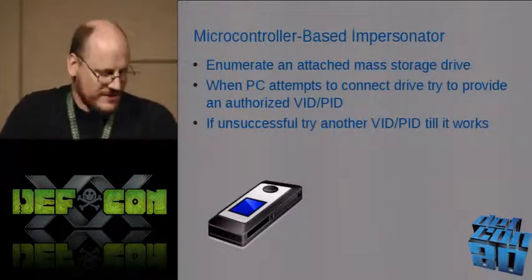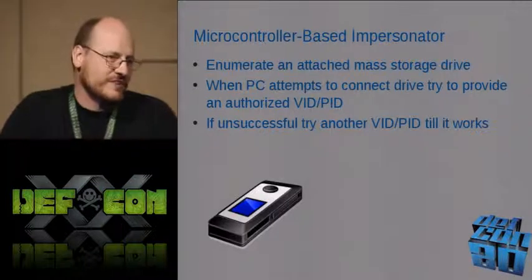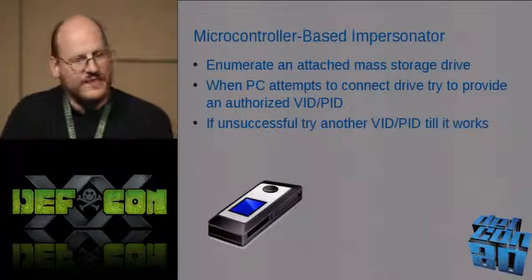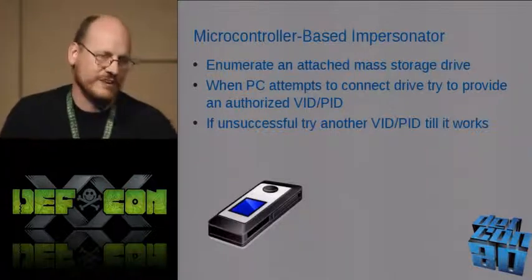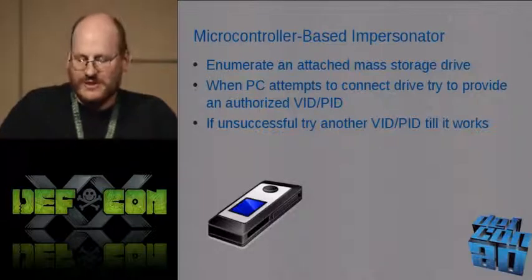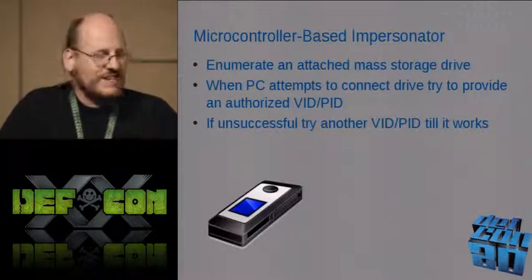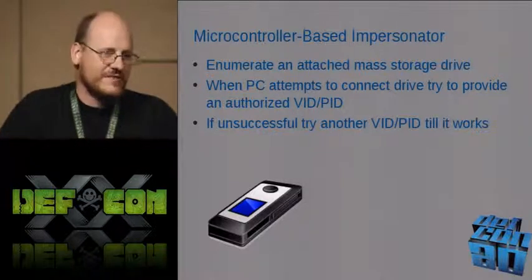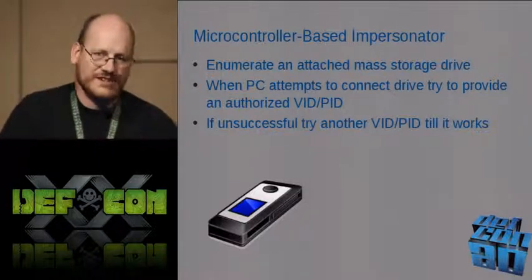What it does is it allows you to insert your flash drive, and it enumerates it. And then when you plug this device in the PC, it says, oh, I see there's a new device. Let me enumerate it, and it tries to get an authorized VID-PID combination. If it's not successful, it tries the next one.